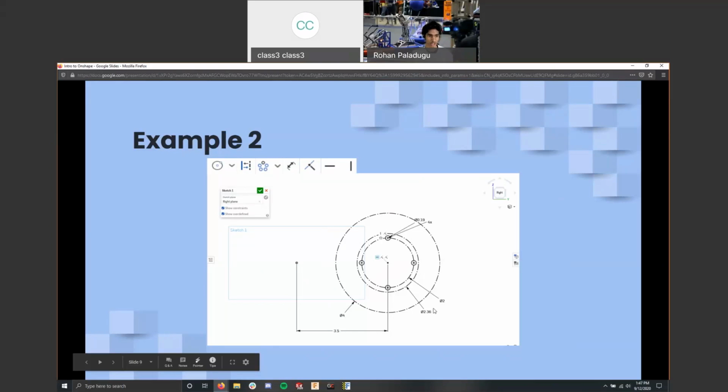You can see its construction. We have our little outer shell of our motor, so that's this 2.36 inches. Specifically, this motor is a Falcon 500. To get that value, I went onto VEXpro's website and got the value from their Falcon 500 drawing. And I inserted it directly in the center because I want this wheel to be direct driven from the motor.